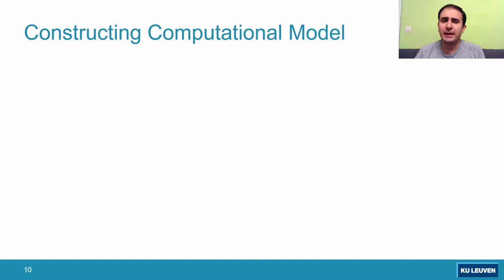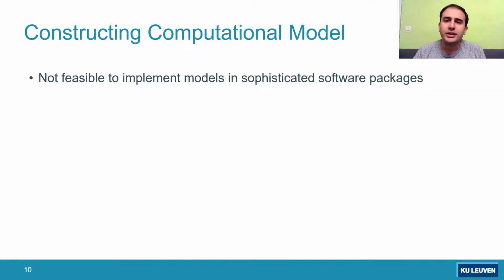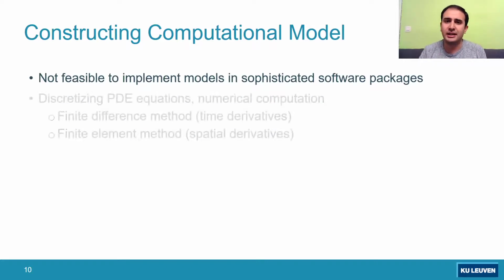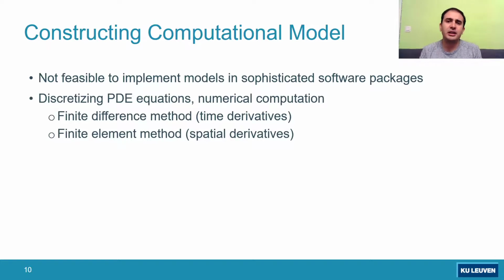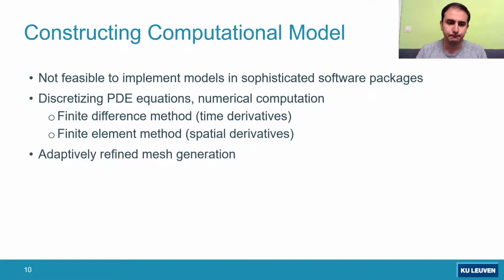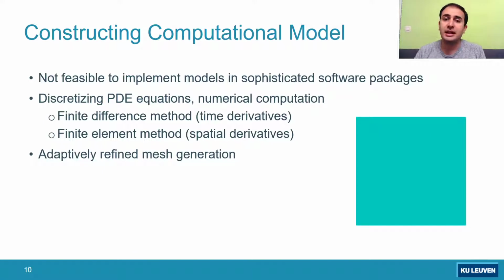After constructing the mathematical model, we need to construct a computational model. This mathematical model is not feasible to be implemented in sophisticated software packages such as Abaqus or ANSYS due to its complexity. As a result, we discretize the PDEs using sophisticated numerical techniques. Finite difference method is used to discretize time derivatives, and finite element method for spatial derivatives. And the mesh is also adaptively refined on the interface to increase the accuracy.